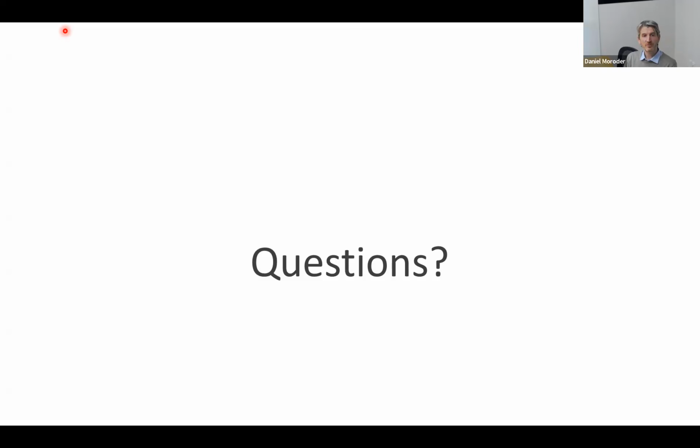Thank you for that. There were a few questions about, let's call it, the stiffness of the link beams when connected to the timber, so I summarized them. First of all, were there any thoughts on the long-term effects? If the timber comes in slightly wet and starts drying, there might be a gap, so is this tight fit of concern? And the second question is, you talk about grout, so we assume it's cementitious grout. Have you considered epoxy grout as an alternative? Wouldn't it be better, considering that cementitious grout would wet the timber around it, therefore swelling it and creating a potential shrinkage problem later on?